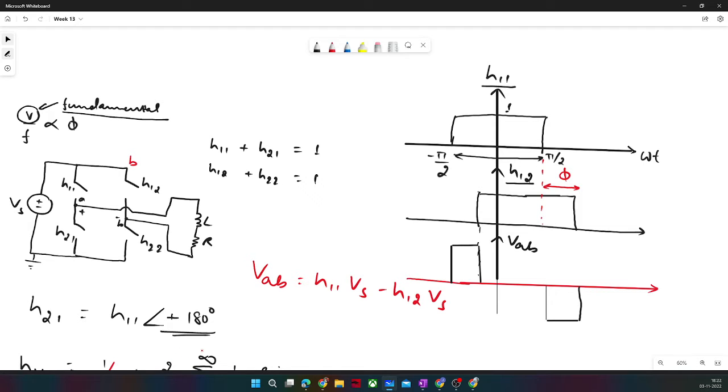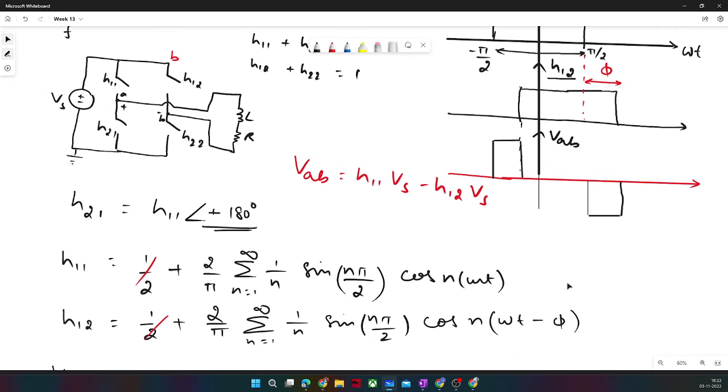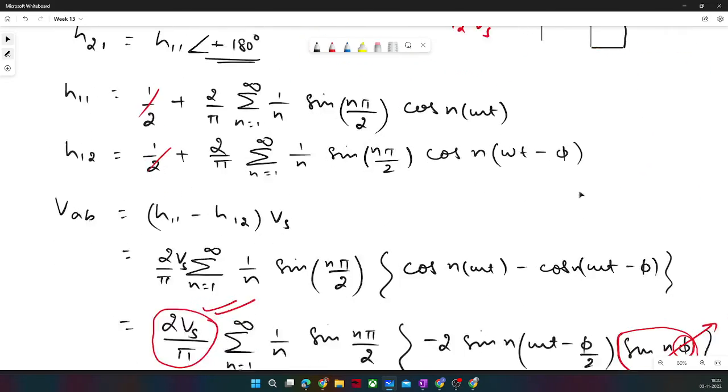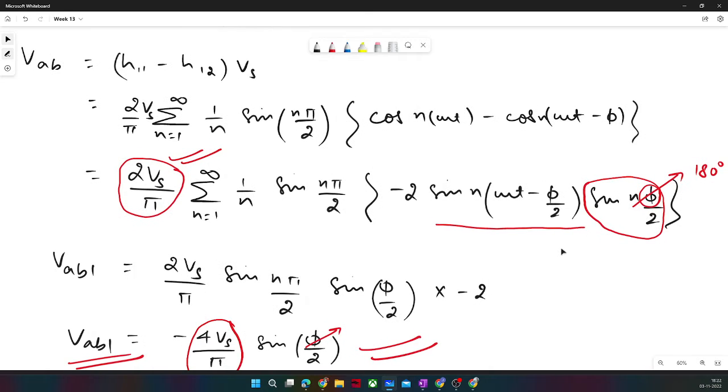You can either control your fundamental voltage or you can control harmonics. You cannot control both fundamental voltage and harmonics. So you have to compromise on a single entity. You have to carefully trade off. Like, if you want to remove some harmonic from this waveform, what do you need to do?